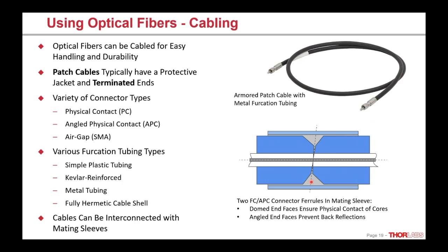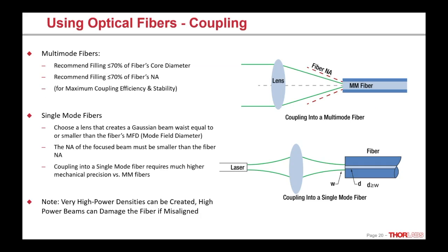Mating sleeves are great, but you can't always go from fiber to fiber. Sometimes it has to be done free space to fiber, fiber to free space. So here we'll give a little data on how exactly we get light into the fiber and how we get it back out of the fiber. Coupling into the fiber is really the same idea with single mode and multi-mode fiber. We use slightly different words just based on the different specs that these fibers typically come with.